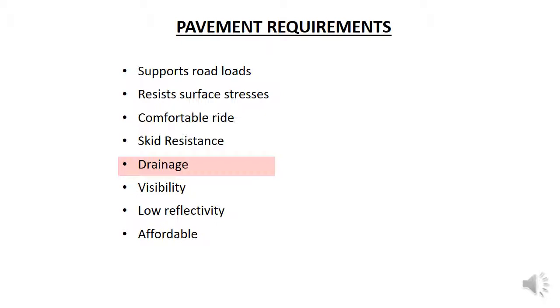Water soaking into the pavement structure can result in the structure not being as strong as it needs to be and failing. Therefore, the surface of the road needs to be watertight to prevent the intrusion of water into the base course.